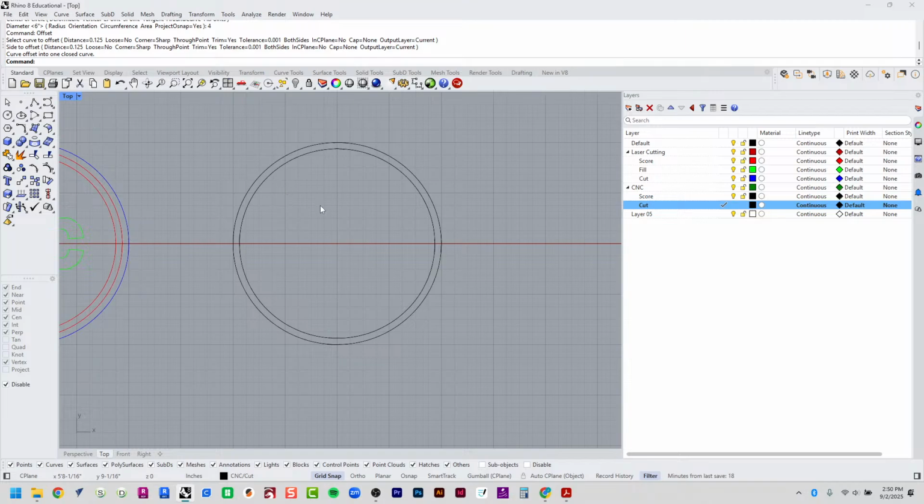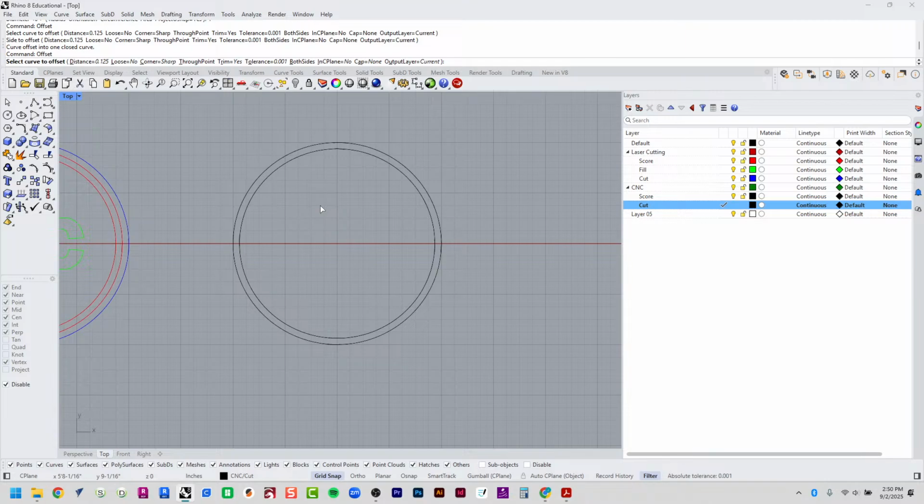Let's say I'm in the mode of creating many things over and over again, and I'm repeating certain commands, right? There's a way in Rhino to just say, hey, let's do that same command again. I'm going to be doing that command many times right now. Let's just repeat it. To do that, there are at least three different options to do that quickly. Option 1 would be to right click. If you right click in Rhino, it actually will act as you pressing enter, right? So if you're in the middle of a command, instead of pressing enter, you can actually right click. Same thing.